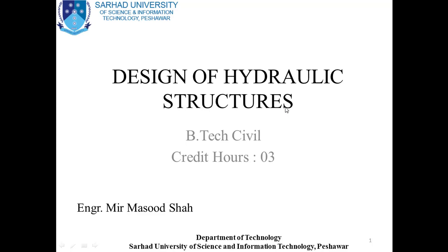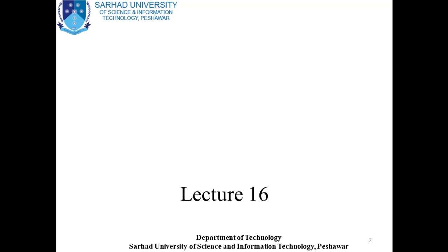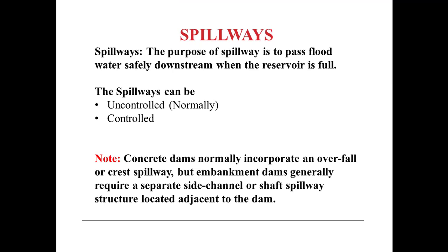As I am teaching you the subject Design of Hydraulic Structure, today is your lecture number 16. In lecture number 16, we will study spillways and different types of spillways. So first of all, what is a spillway? The purpose of a spillway is to pass flood water safely downstream when the reservoir is full.